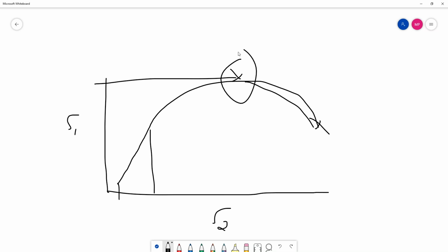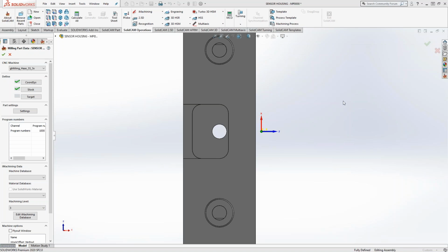So this is the value that you're going to get, like Kevin said, from a database or from your material supplier. This is where the chip begins to actually form. Basically, you've cleaved the material with that flute, and then eventually that thing is just starting to bend enough that it'll just snap right off. But this is where we need to know where the material is actually going to do that. So that's what ultimate tensile strength is. That's just real quick there.